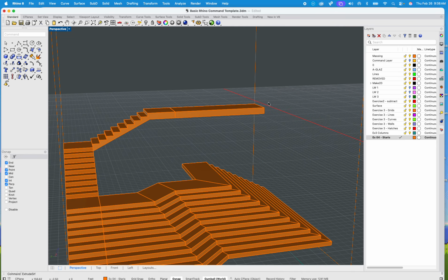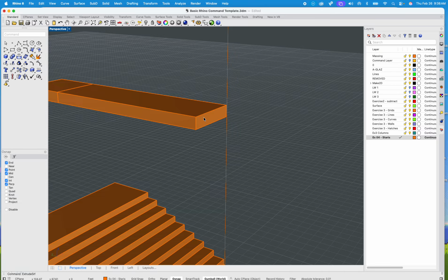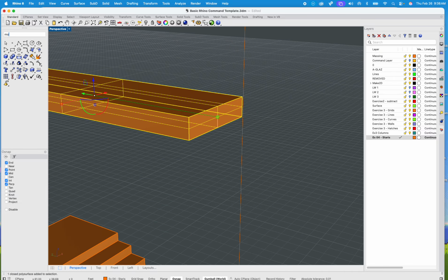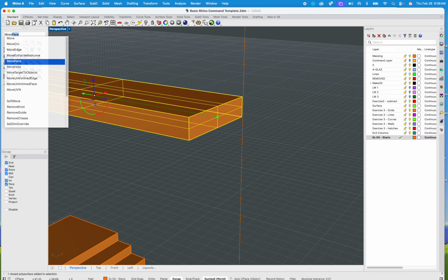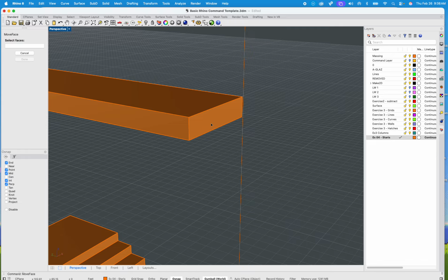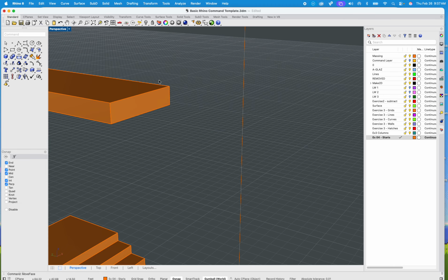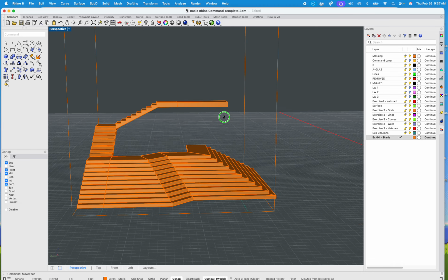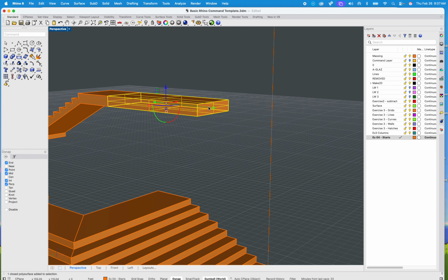I definitely did. However, if you need to take it back, Move Face could also be used. Right? So we can do Move Face. So if there's anything to write down today, it's definitely Move Face and Extrude Surface. Okay? But we can potentially move this back as well. So maybe we want exactly 4 feet. So I'm going to go with 4 feet, hold shift, and voila.